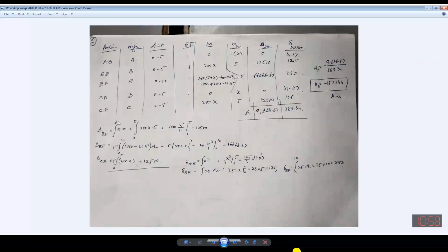On the same lines, only one displacement is needed as far as the actual structure, the primary structure, the actual loading is concerned. This will be delta DH, and if you multiply M into m, then you need to apply the limit, and over there it will be integrated. There will be dx over there.